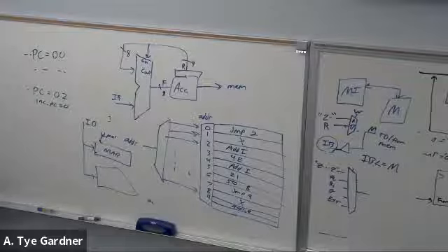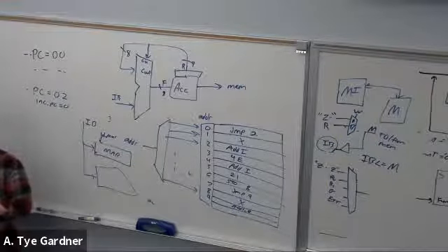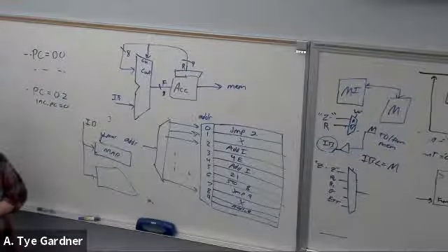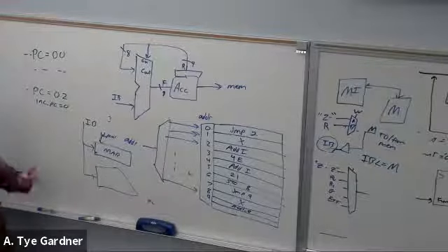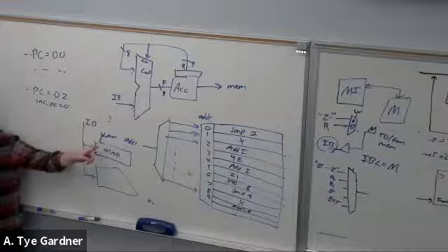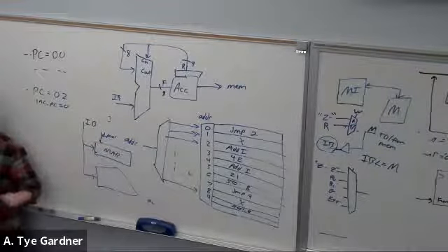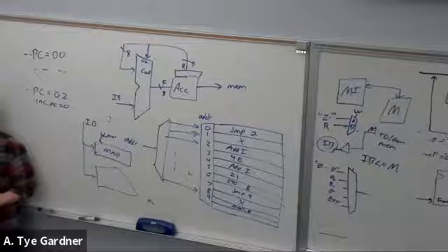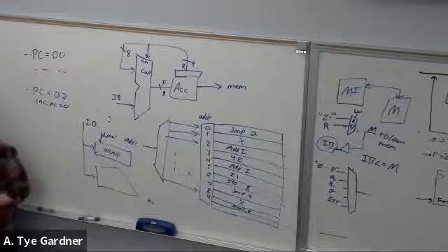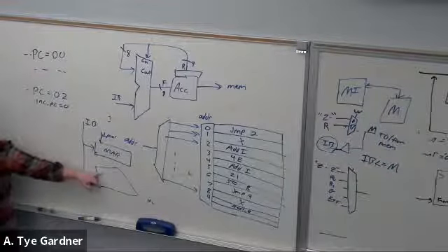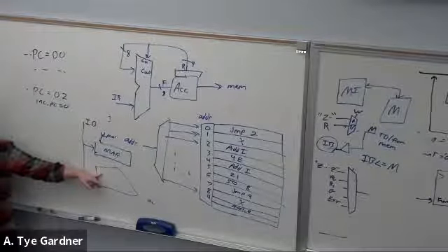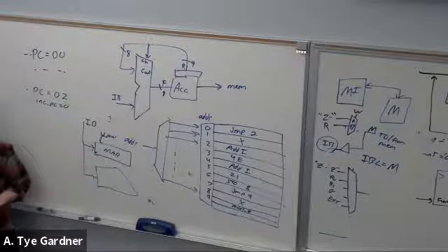Okay, any other questions on the microprocessor at this point before I transition to state machines again? I have a quick question. So VHDL, how do we design the MAR and PC? Well, the MAR is just a register, memory address register. Just a register. So it's just Q equals D, right? If rising edge of clock and load MAR, Q equals D. Done. The PC is just a counter with parallel load, which we've designed counters for homework, right?